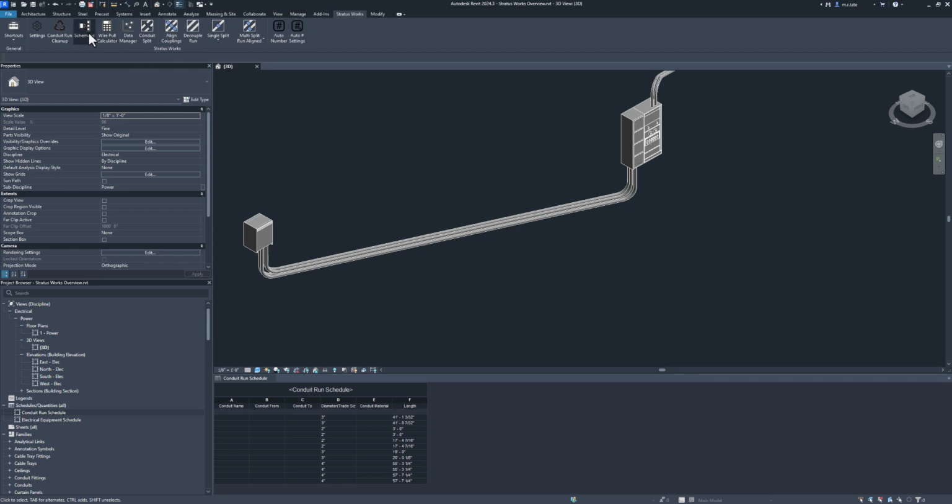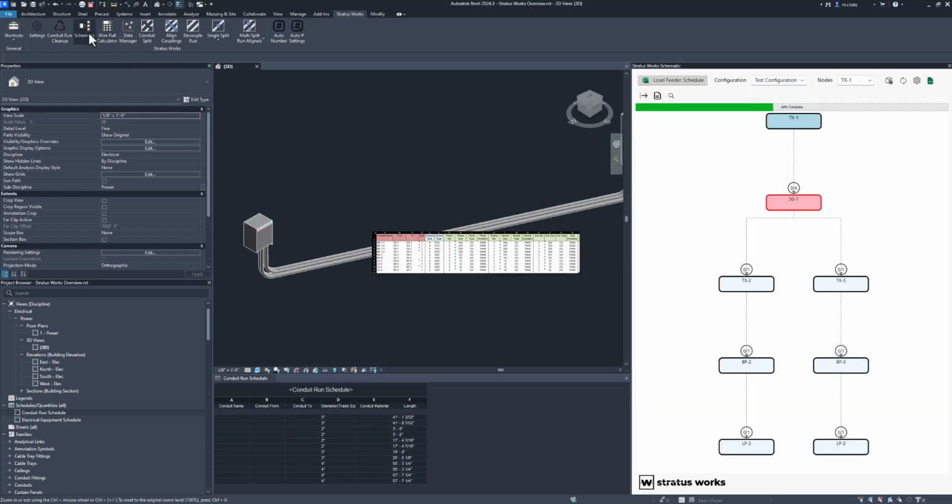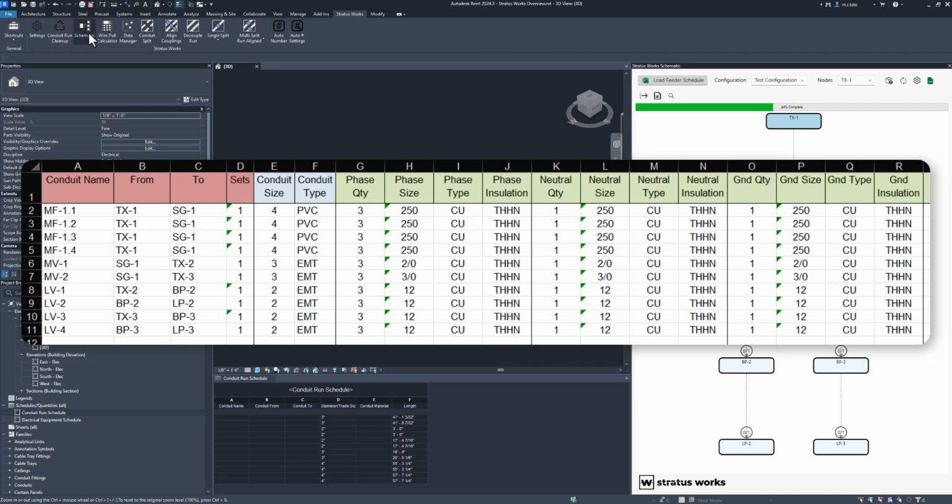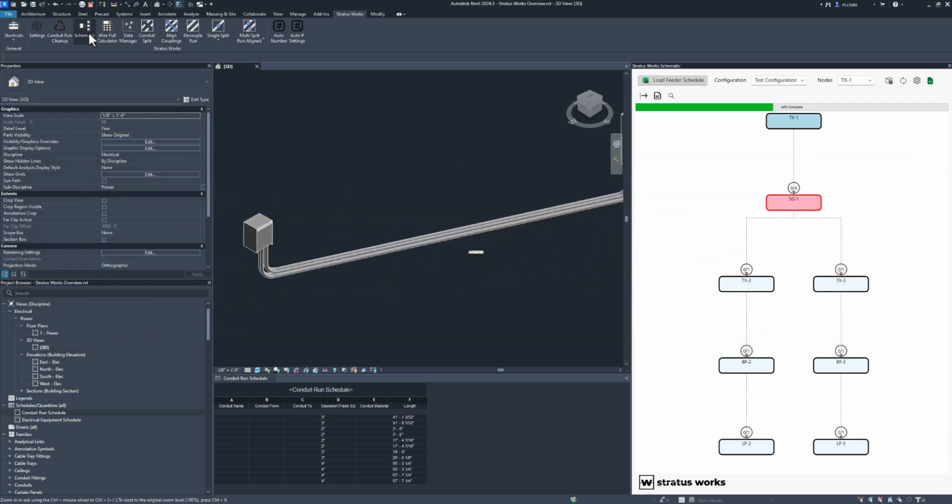The Schematic Viewer and the Feeder Schedule Import feature allow you to map feeder schedule columns in an Excel document to Revit parameters for use in imports and exports from the Revit model. Part of this process ensures system designs align with project requirements, as well as allows a QA/QC operation in accordance with that engineering design. What we see on the right here is a simplified single-line drawing that's derived from that feeder schedule. This tells us equipment that we need to connect to, whether or not that equipment is in the model, and when those connections have been reconciled with the feeder schedule.